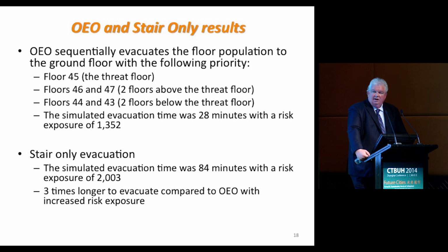So if you're using the occupant evacuation operation approach, it'll sequentially evacuate the floor population to the ground floor with these priorities. Floor 45 is the fire floor. Then it does the 2 floors above and the 2 floors below.